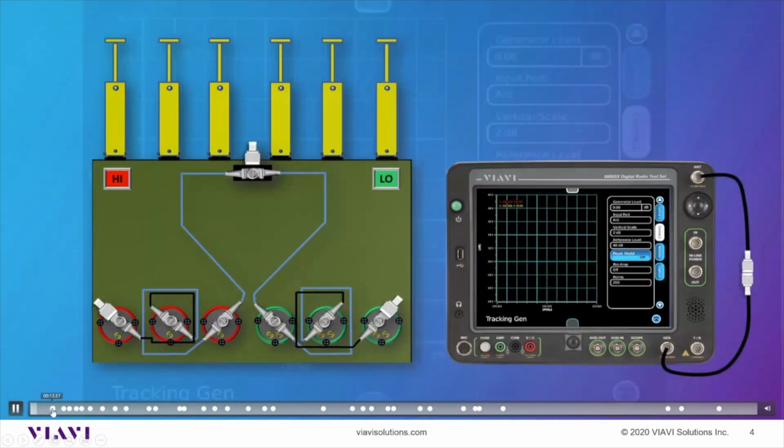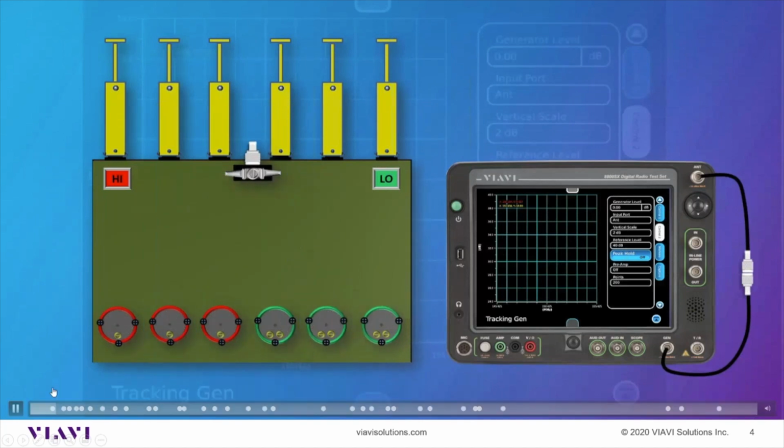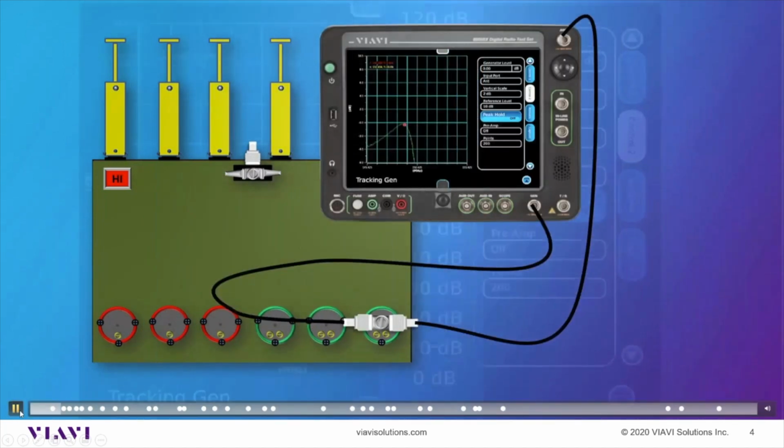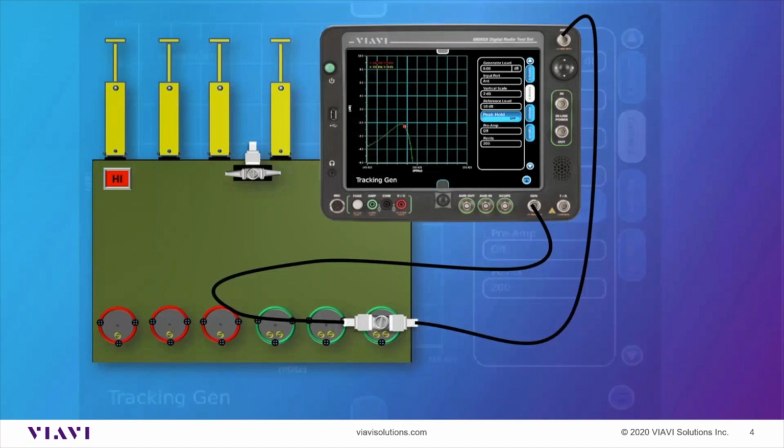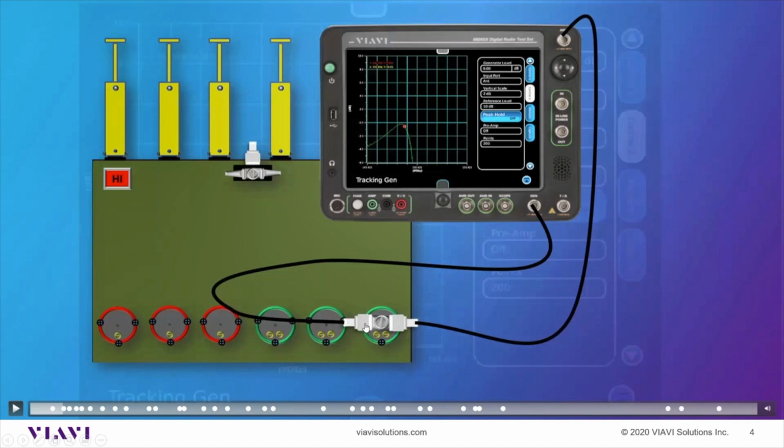So the first thing you've got to do if you want to realign your duplexer is you've got to take the cables off. And so I'm just going to easily take them out of the picture here, so we can see what's going on. So you're going to put a T on your 2 cables that you just did the set reference on and referenced out all of the loss in those cables. You're going to put a T connector on those. One side of the T is going to go to the generator port. The other side of the T is going to go to the antenna, and the third port on that T, or the middle port, is going to be connected to the resonator cavity.